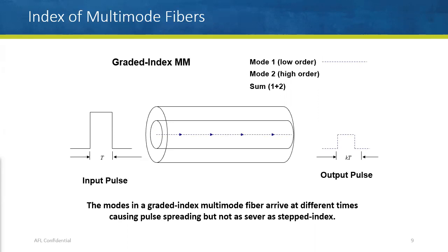With the graded index, we get a similar functionality, but now because we've used different types of glass concentrically through that center, through the core, we can now slow the light down that's going right down the center and use a faster glass around the outside so that the pulse gets there more in time with itself.